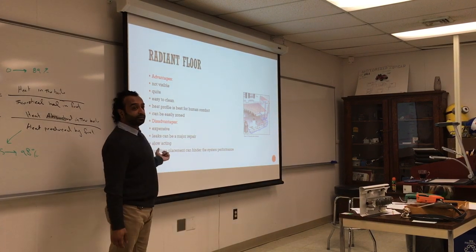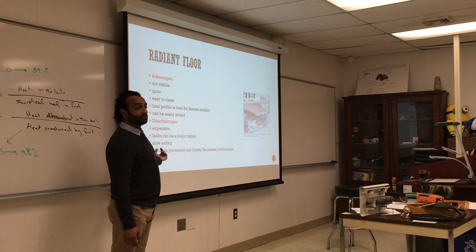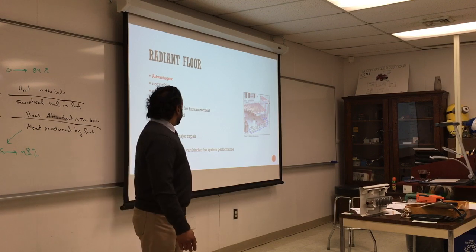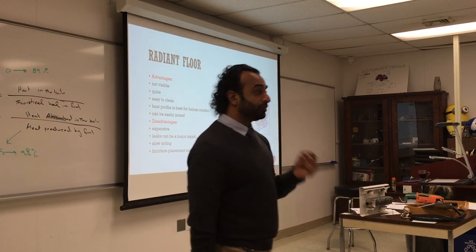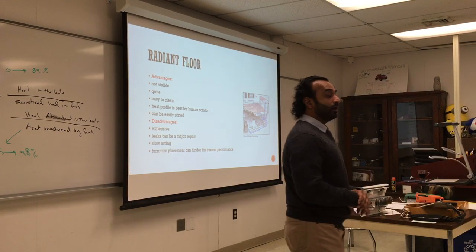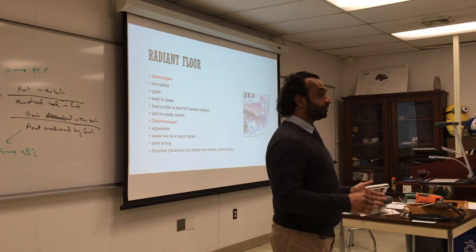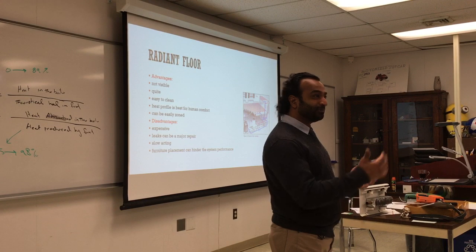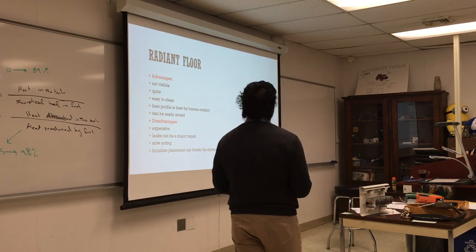It's slow acting, but it's something you keep on for the entire season, because again, it's really not that much heat. And furniture placement can be a problem, so you have to think about that. If you're going to heat the floor and you're going to put tables and couches and rugs and stuff, that's not going to be productive to heat the floor. So it's mostly for plain hardwood floor or concrete floor without a lot of furniture. Otherwise, it's going to hold back the heat from coming up.